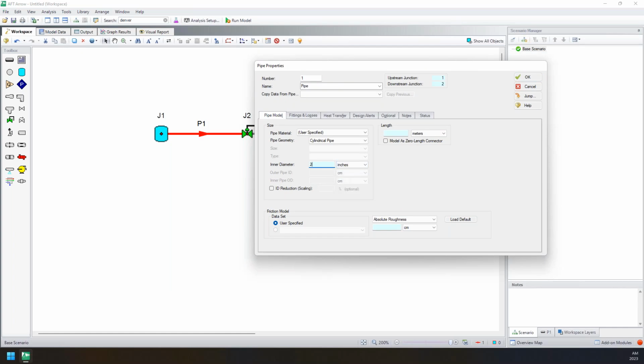So if we wanted to model a 2-inch pipe that's 3 meters long, and maybe we estimate a roughness of 0.0001 centimeters. Obviously, that manual input can be a lot of information for the user, and also it can be very error prone. Maybe I misspecify the units and now my solution is invalid. So one way that we try to resolve that is AFT does provide a pipe material database for you. And these are generally customary sizes or sizes consistent with standards.